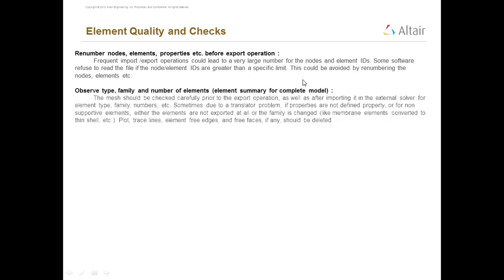Renumber nodes, elements, property, etc. before export operation. Frequent import-export operation could lead to a very large number for node and element IDs. Some software refuses to read the file if the node or element IDs are greater than a specific limit. This could be avoided by renumbering the nodes and elements.